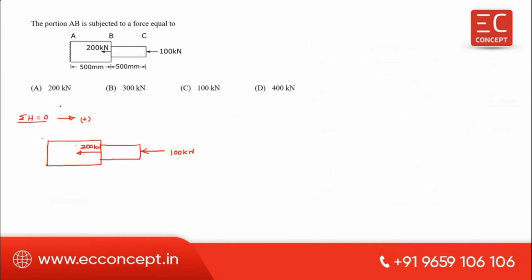Now, this is the fixed rigid end. Therefore, there was a reaction force. Let me assume this is RA. We can assume our right side is positive for sigma h. Therefore, RA minus 200 minus 100 is equal to 0. Therefore, RA is equal to 300 kilonewton. We got RA. Now, they are asking for the force in portion AB.